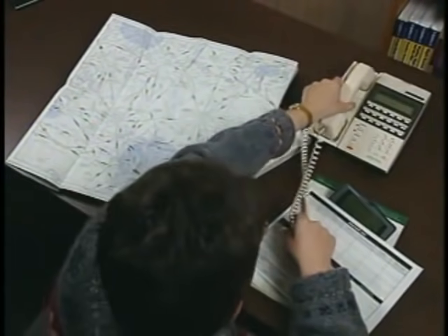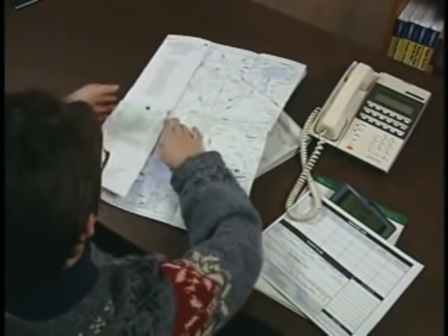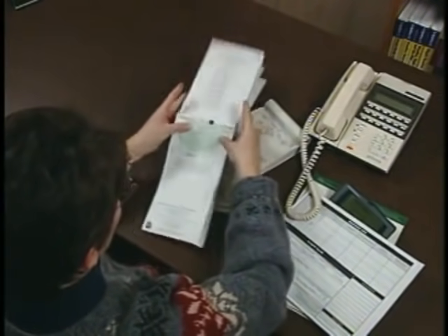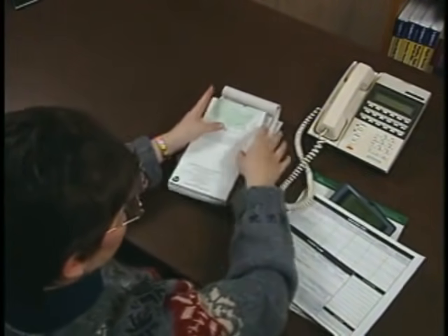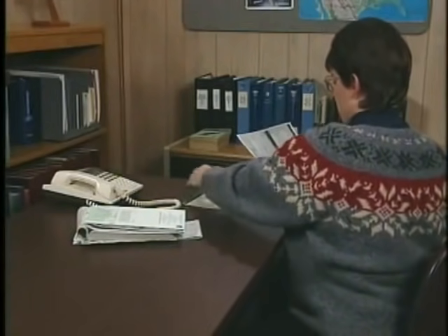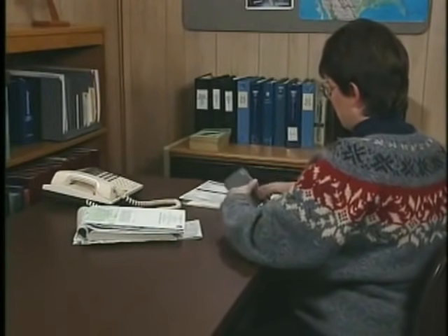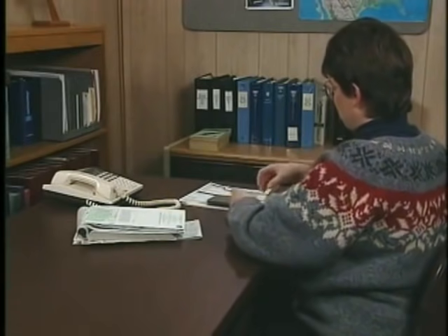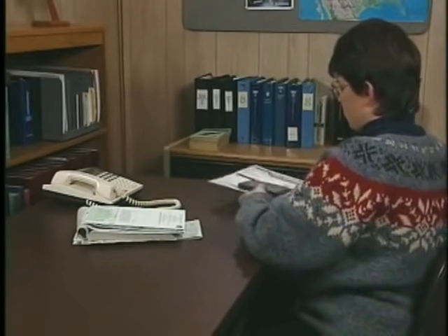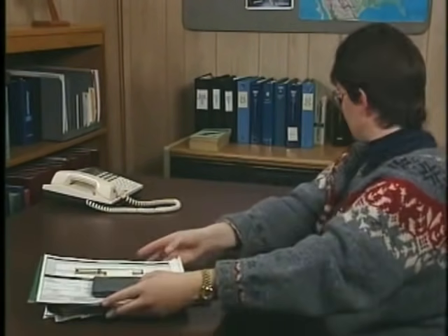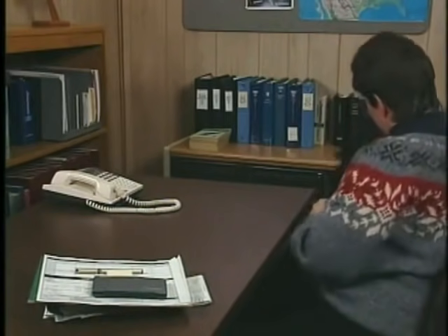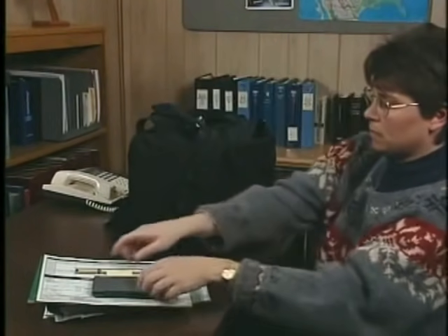Standard terminal arrival routes expedite your descent from the en route structure and position your aircraft at a point where you can begin an approach. Unless you indicate no STAR on your flight plan, ATC can assign one anytime they need to. Being familiar with these procedures will enable you to fly IFR into the most congested airspace with confidence.